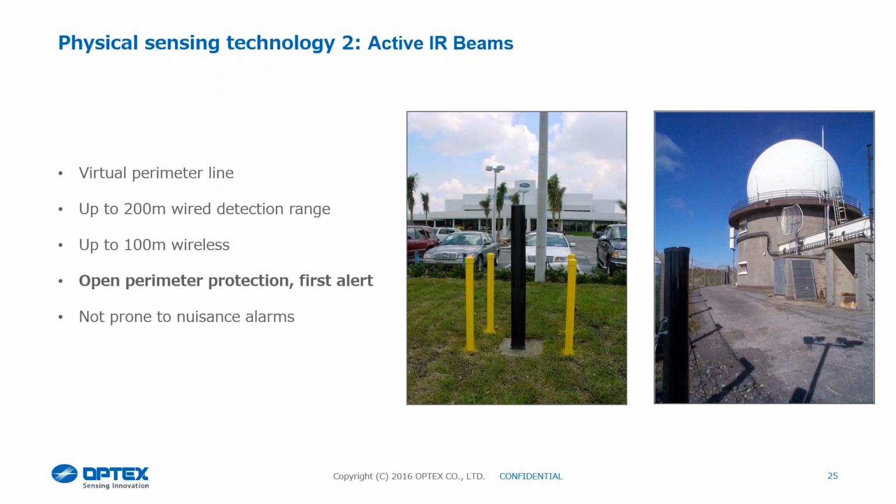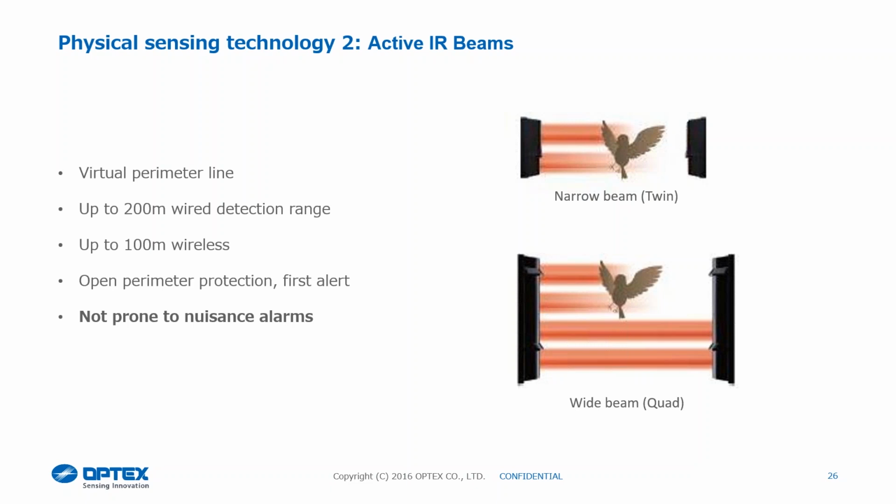Again, we do the pre-building for you. We wouldn't want to send the bits to site for your engineer to try and put them together and make sure they all work. We can do this for you in-house, have them sent to site ready for the guys to, as I would call it, screw to the wall and commission, and they're ready to go. These are a very, very solid detector for you. As you can see by the images, you can have the odd pigeon go through, that's not a problem. And we have the dual beams, which are the AX version, as I say, or the quads are the SLs.